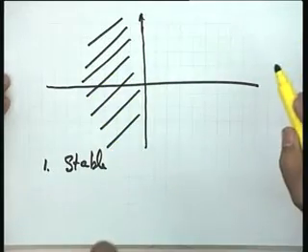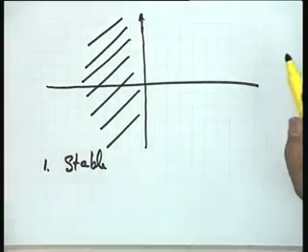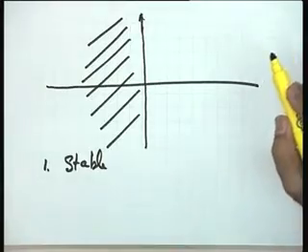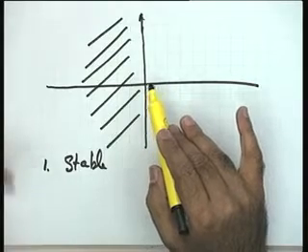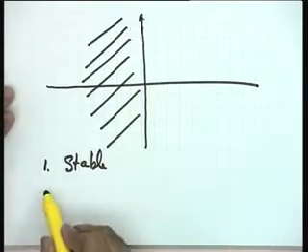You will call that particular system a stable system, though we had derived, if you recall, the asymptotic stability and BIBO stability, these two definitions were given, but then I made a statement that in the most commonly occurring situation, the two are equivalent. Therefore, we will drop the word BIBO or asymptotic, we will consider the system to be a stable or an unstable system. A system is stable if all the roots of the characteristic equation are in the left half plane, all the roots, I am referring to this point.